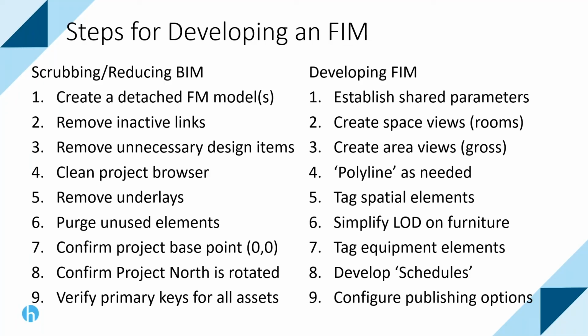But we recommend that you do this. You can take your BIM models, scrub them, and reduce them down into a very simplified version that you're going to use for operations. Add your space views, your area views, your equipment in the format that you need, the schedules if you want them, and make sure that the publishing is set up to work to Archibus. And then what you have is a facility information model that you can use for Archibus and link to Archibus